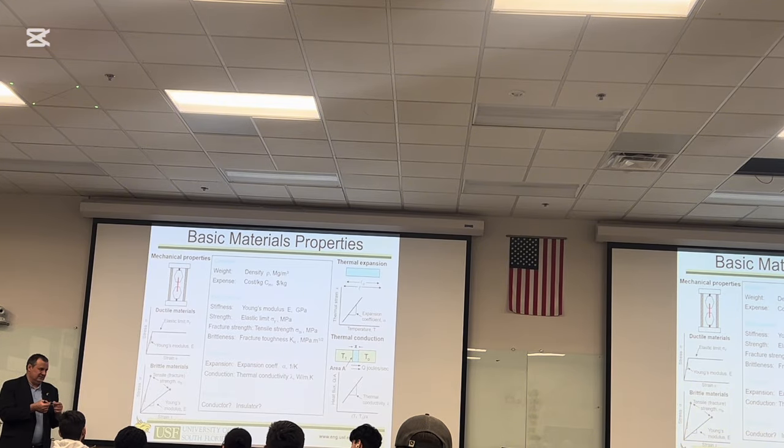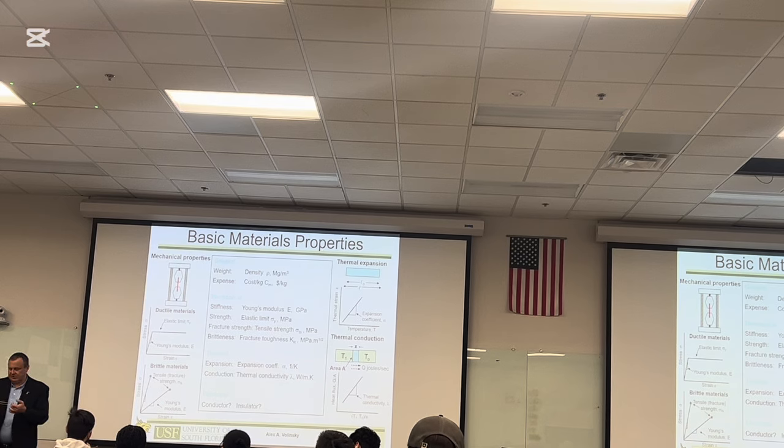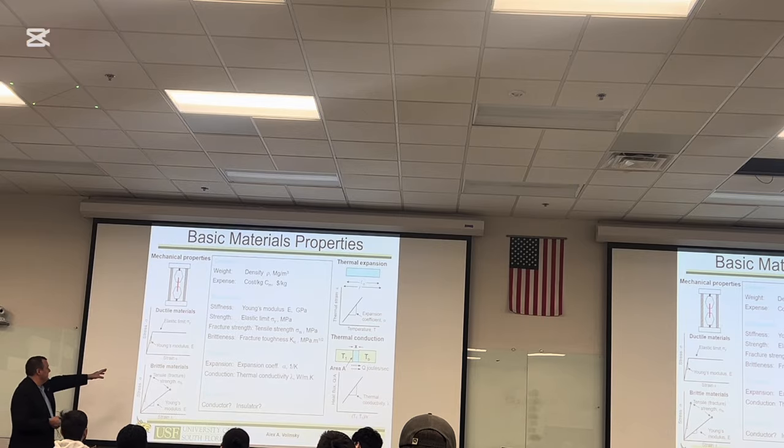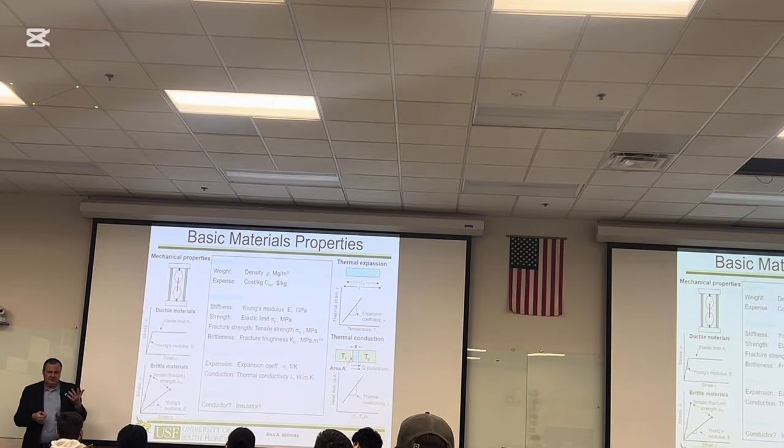And what units would you get? PSI. Okay, units of pressure, which is newtons per meter squared. Where do you get meters squared or inches squared? It's okay, no problem. The stress has the units of pressure, so it's newtons per meter squared. If we take the cross-sectional area of this rubber band and divide the load by the cross-sectional area, that's going to give us normal stress. That's what you see over here, stress. And sigma means that it's normal.